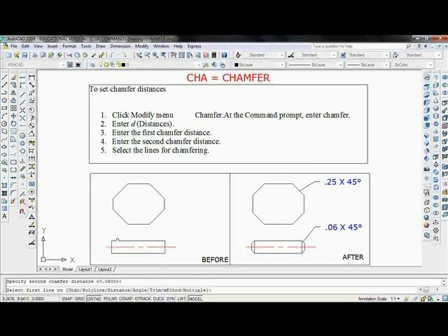So now I'll select the corner, repeat it down there, and again on this side, and again here. And since this is a shaft, and looking at it from the outside, there should be a line here. So I'm going to put a line with object snap on from here to here, enter, repeat the command from here to here. And the drawing looks correct, so we'll move on.